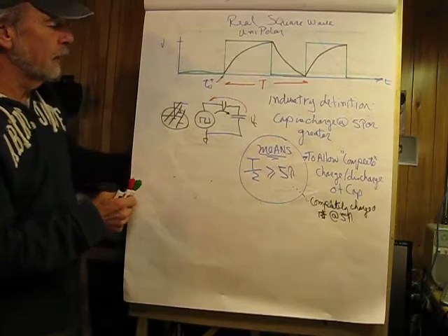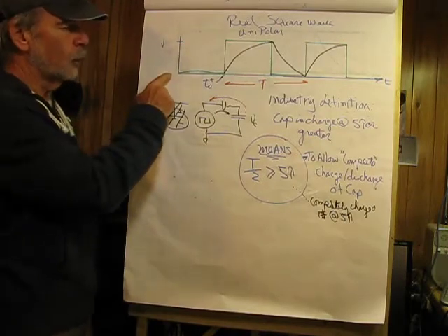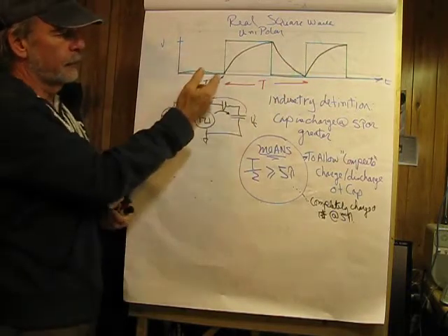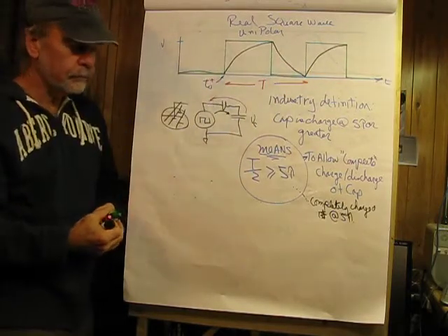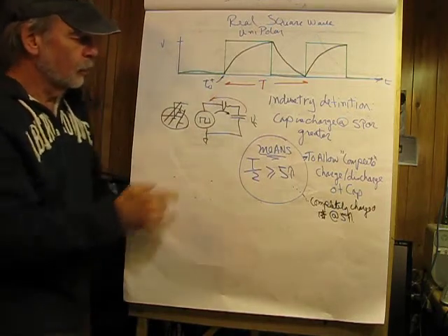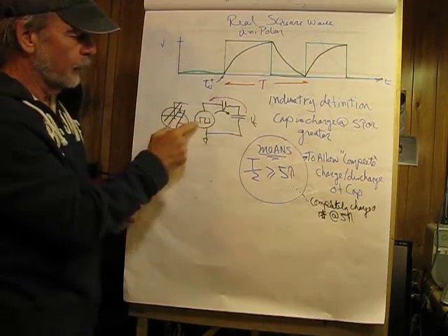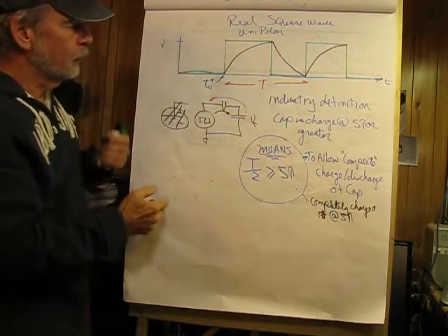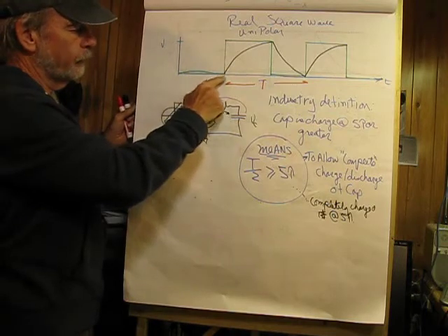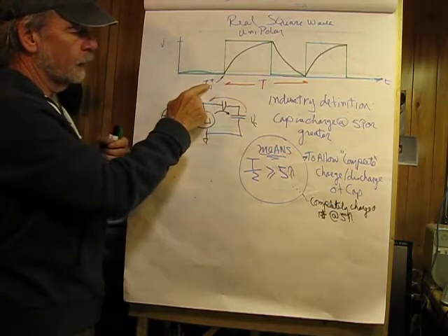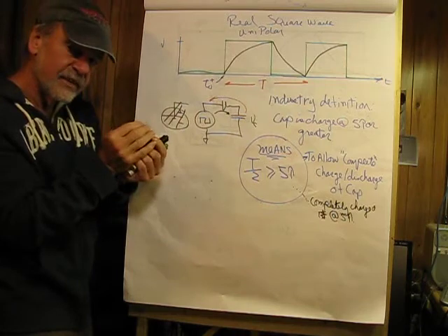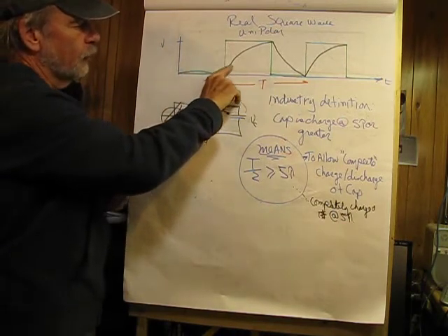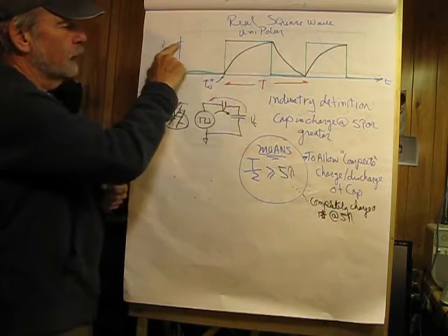We're not going to see that. And this is a real square wave where I'm showing the rise and fall times here, and even though this looks to be vertical, it isn't. And we're dealing here with a square wave source, unipolar again, only goes in one direction. And what we're seeing here is that, starting out here at t0 plus, which is a super small instant at a time when this goes high, the capacitor will start to charge toward the final voltage here, which is V.